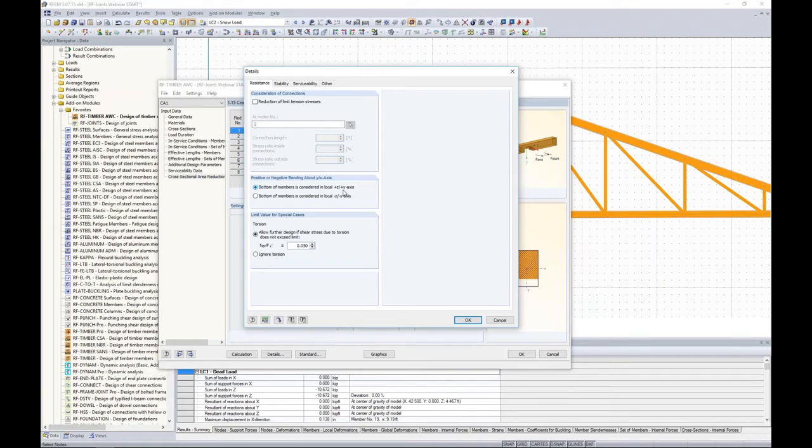What this is used for is for glulam beams. They always have different bending design values for our top versus our bottom and tension, and whether our moment is positive or negative. So by default in the program, the positive local axis for Z is pointing down for our members. So typically you won't be adjusting this unless you're rearranging the local axes of your members. So that's just what that is in reference to for our glulam beams.